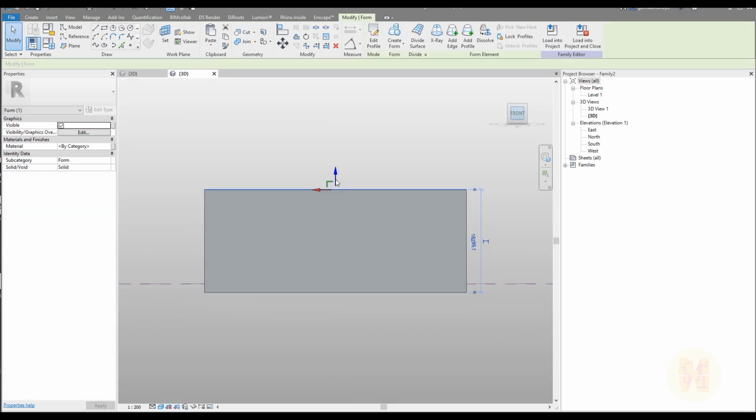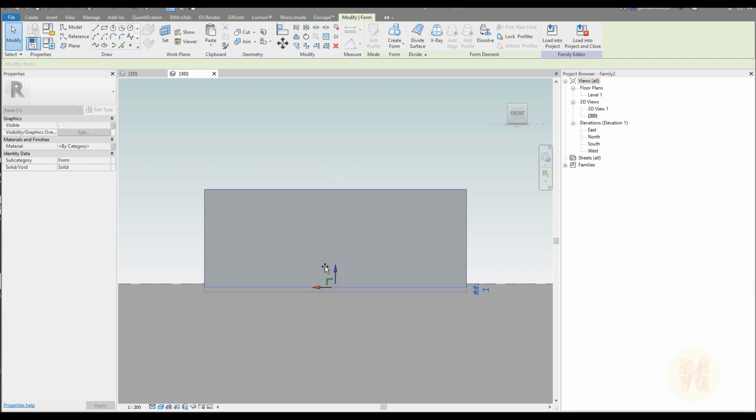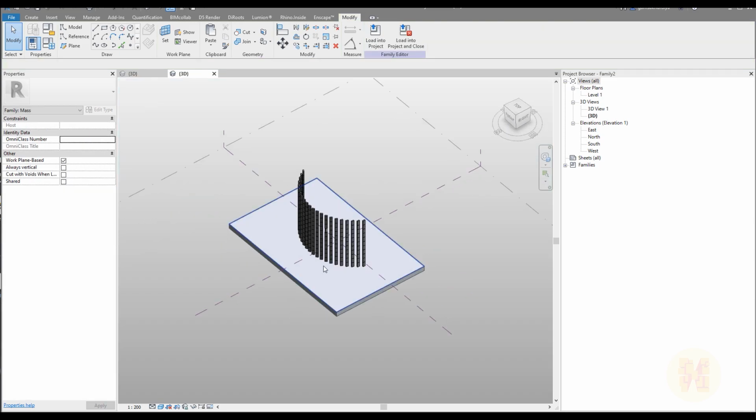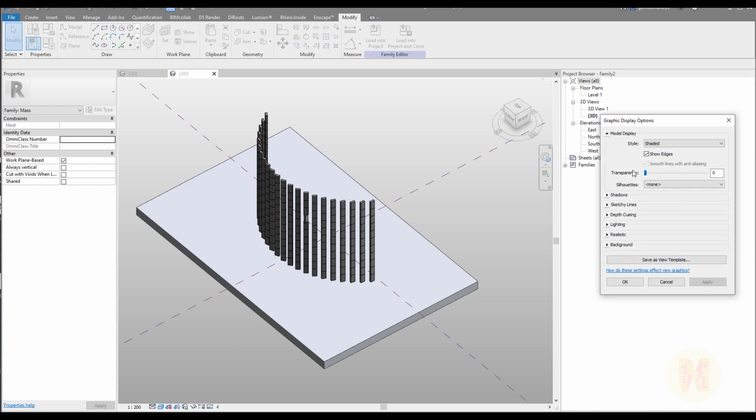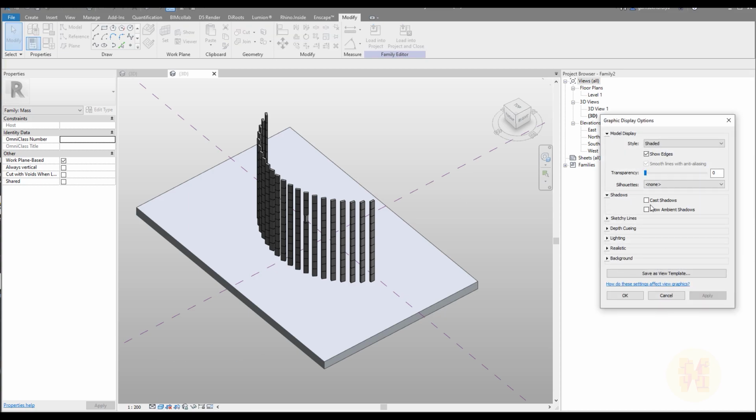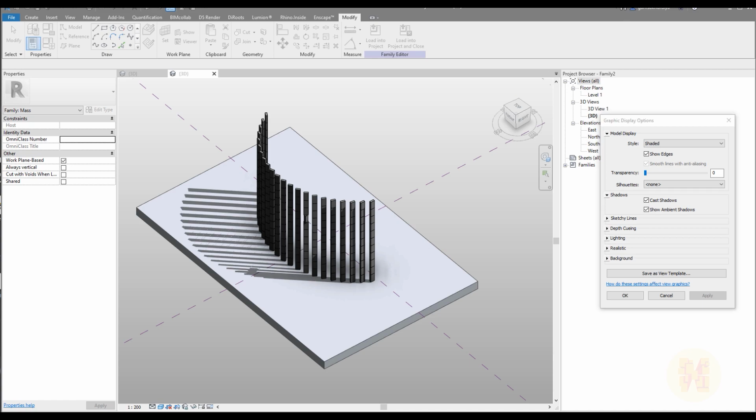I wanna see only this part on this side. Okay. So I will switch on my shading. Here are the shadows, cast shadows, applied, and as you can see it's here. I will just change my sun. Now sun is going from this side. I wanna change it. It's going from that side.